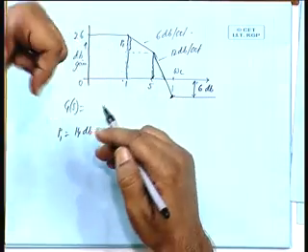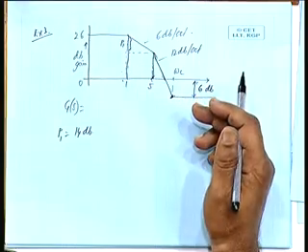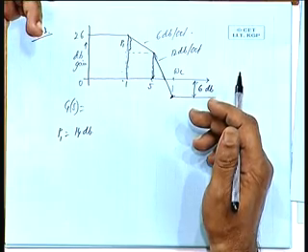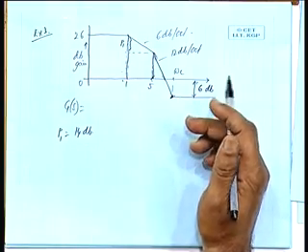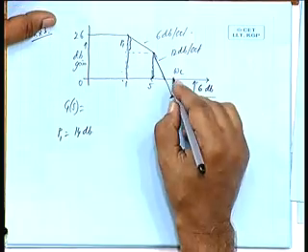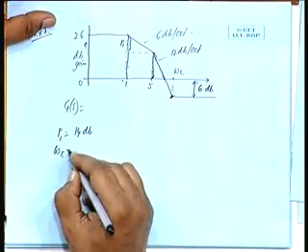If it is a multiple of 6, then you take the octave threefold, 5 to 10 one octave, 10 to 20 another octave, 20 to 40 another octave. So, every time per octave you are having an increase of 6 dB, 6 dB, 6 dB like that. So, for an 18 dB there is any multiples of 6, the calculation is very simple, is it not? So, 5, 10, 20, 40, okay. So, omega c is 40.